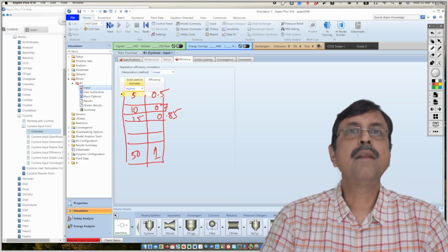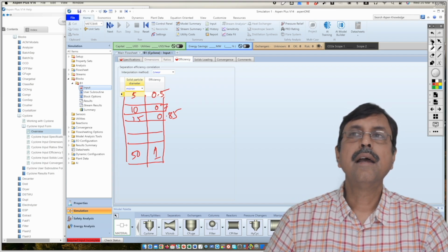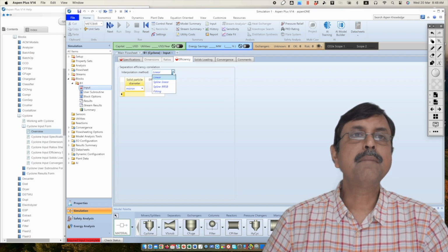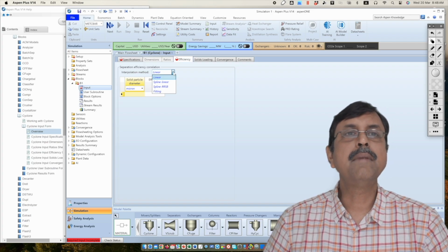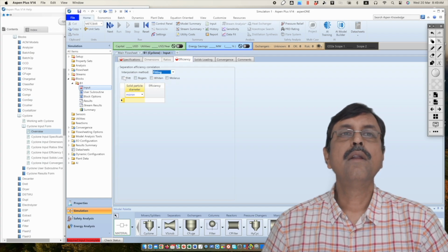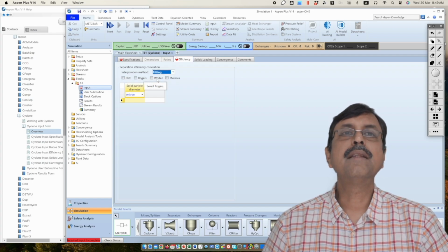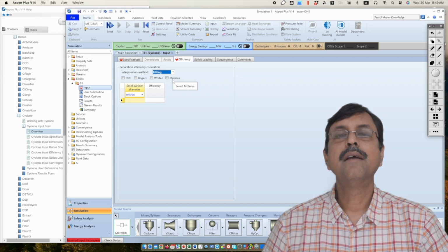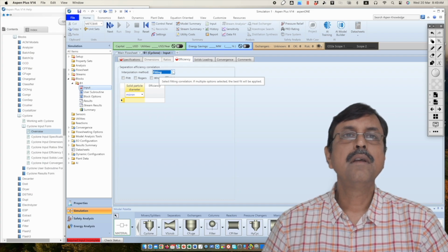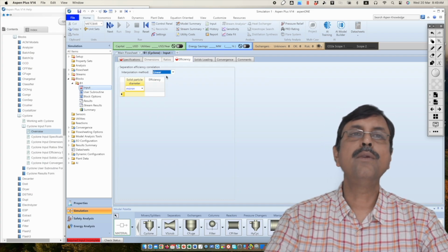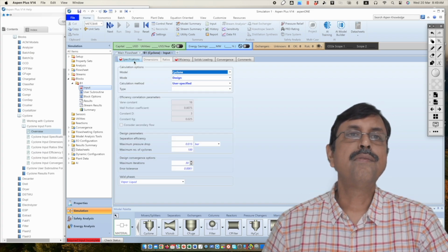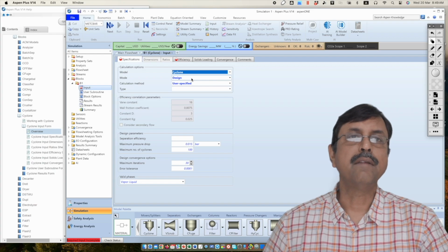based on your experimental work, then the Aspen Plus will do some interpolation. And this interpolation method may be any one of them. It may be linear, it may be spline linear, it may be spline RRSB or fitting. In fitting, these methods are known to you: Plitt method, Rogers method, Whiten method, Molerus method. You already know what they are. So you have to use any one of them for a good fitting, and you can use that particular separation efficiency correlation for your simulation or design, whatever.